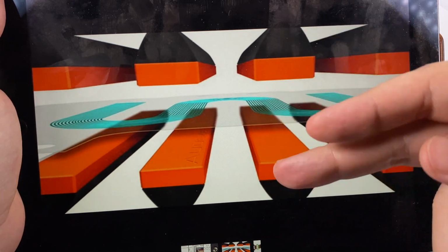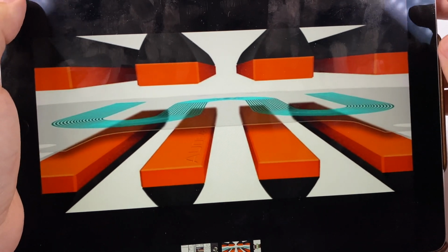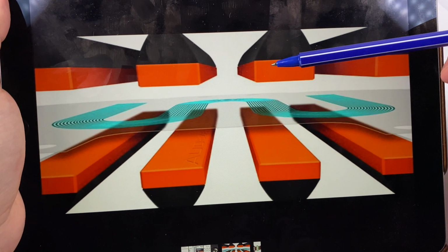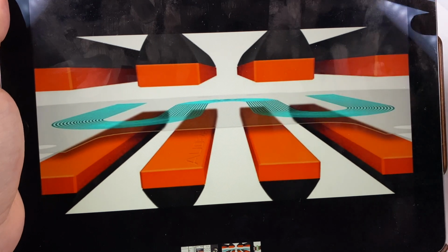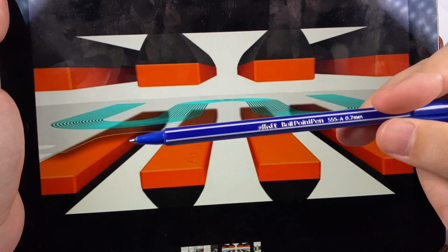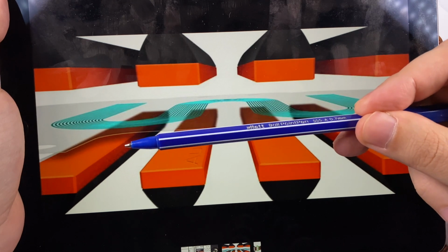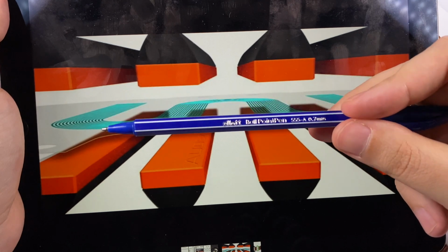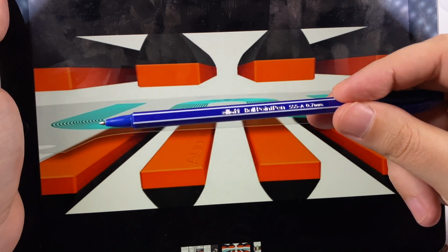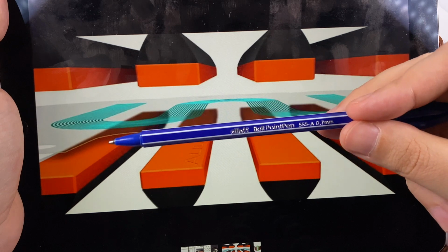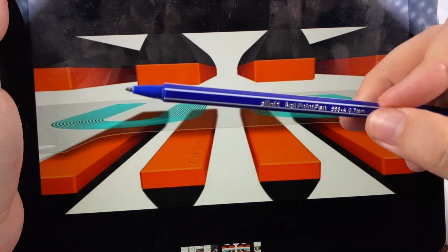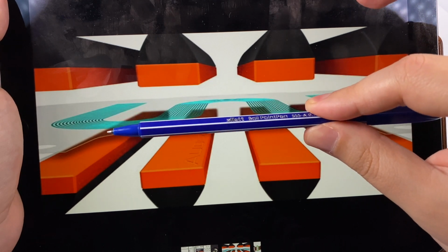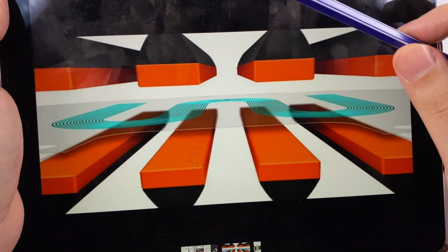So conductive wires, we apply the current to these wires, we get an alternating magnetic field, and it will start moving in the static magnetic field. What are the pluses of this schema? First plus is that the magnetic field is almost uniform here, so it's easy to achieve almost linear movement of the diaphragm, especially when it has some special shape with some ribbing or something like that. So we've got less distortion, the diaphragm moves in a more uniform way, we've got piston-like movement, so we've got a lower level of distortion and we've got higher resolution.